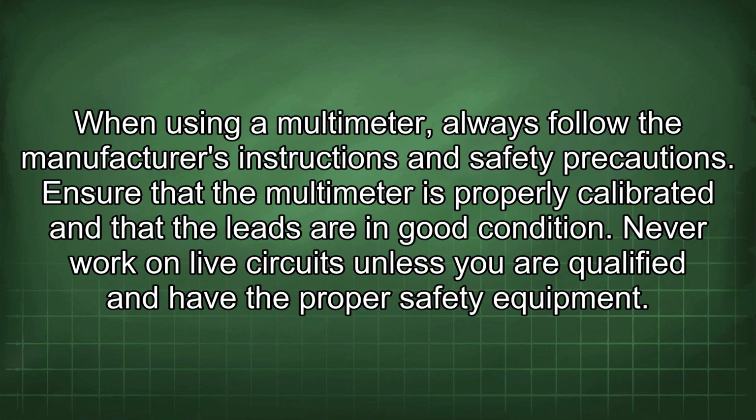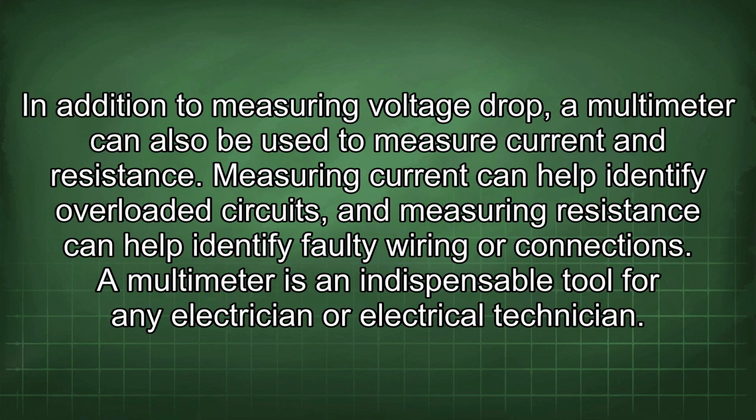When using a multimeter, always follow the manufacturer's instructions and safety precautions. Ensure that the multimeter is properly calibrated and that the leads are in good condition. Never work on live circuits unless you are qualified and have the proper safety equipment. In addition to measuring voltage drop, a multimeter can also be used to measure current and resistance. Measuring current can help identify overloaded circuits, and measuring resistance can help identify faulty wiring or connections. A multimeter is an indispensable tool for any electrician or electrical technician.